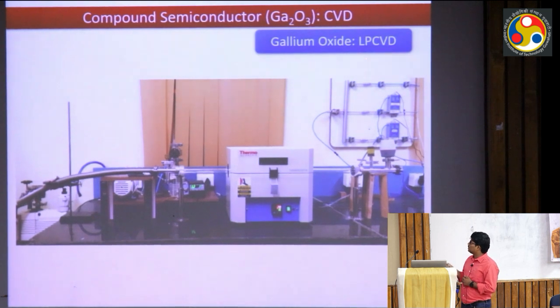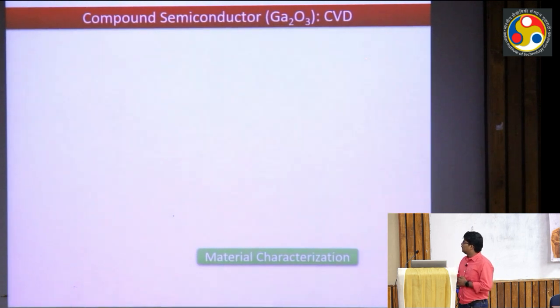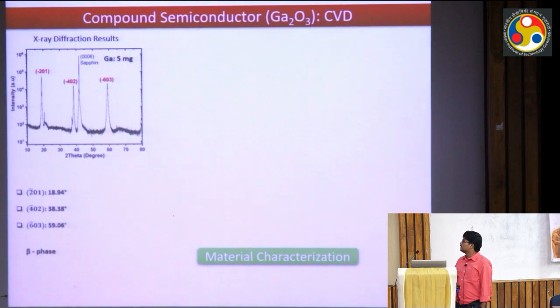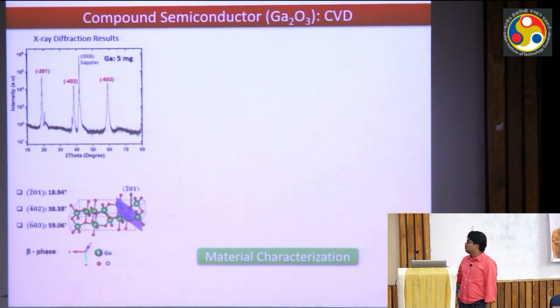So this is how this system looks, and then we have done some characterization also after depositing this gallium oxide. Again, we confirm that we are getting very good crystalline quality gallium oxide using this LPCVD technique. So from this XRD, we can confirm this.